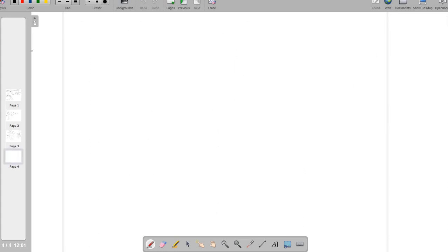Next, stiffness matrix for element 2. So it is K2. The area is not going to change. Young's modulus is also the same, and the effective length is also the same. So you can write 28 into 10 power 3.